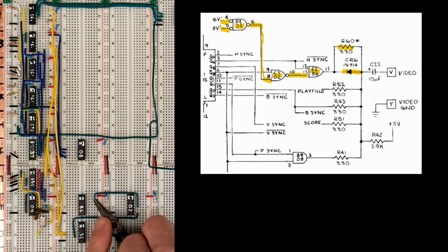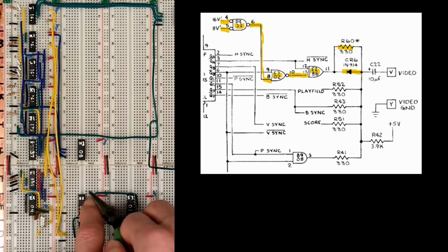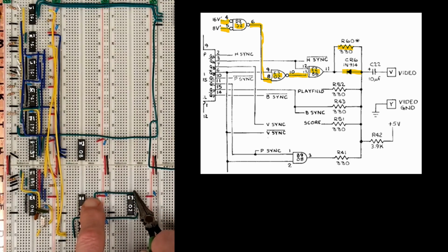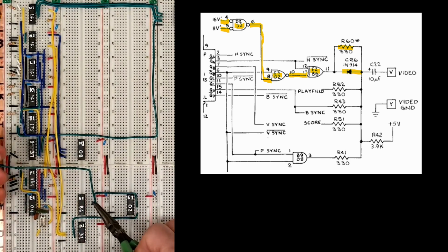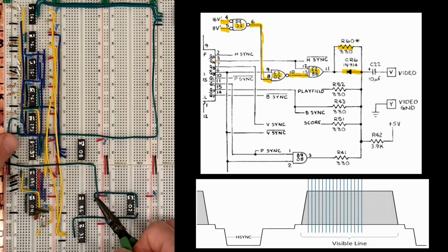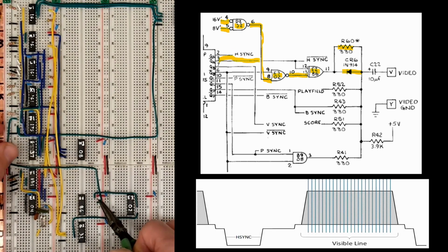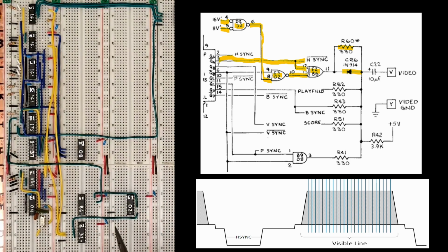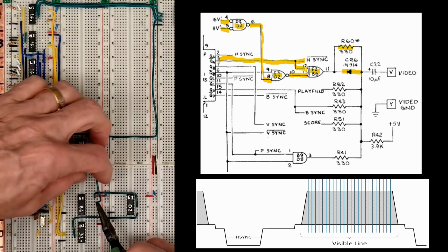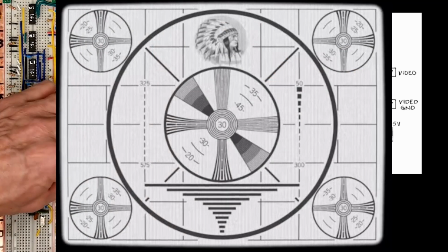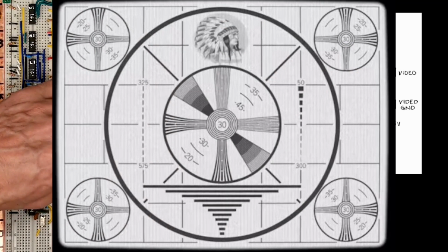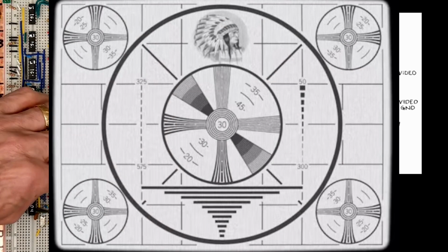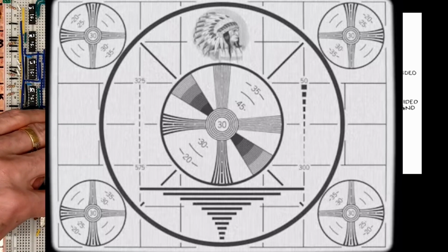There's only a horizontal sweep at a certain rate and the monitor's ability to control the electron gun. External systems driving a CRT define what pixels are by breaking up the physical portion of each line into as many pieces as desired, as long as the monitor can handle it. That's why they have these test patterns. You can easily see where the monitor can only handle up to a certain rate of input changes. Then the lines start to blur together.